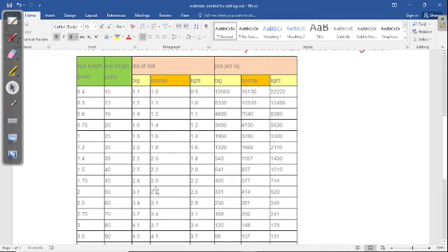We're actually using the normal size, so the diameter of the normal size will be 2.8 in millimeters. Now, when you go to number of pieces per kg, you have 414 pieces of that normal 2 inches nail in 1 kg, which is more than sufficient for what we need.